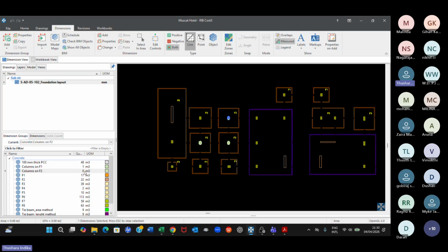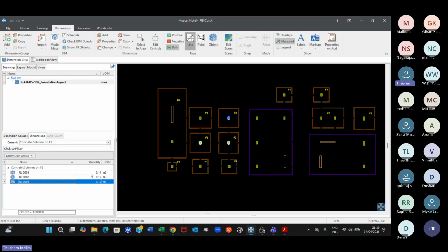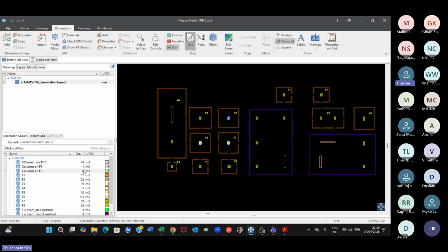This is counter for rounding off here. So when you put into the BOQ, you will see what is going to happen. You can change the decimals there so that, if you want, you can even get decimal numbers in the BOQ. Though this shows as a 0 value, actually all the quantities have been captured here. So don't worry. It is less than 1. That's why you see 0 here.